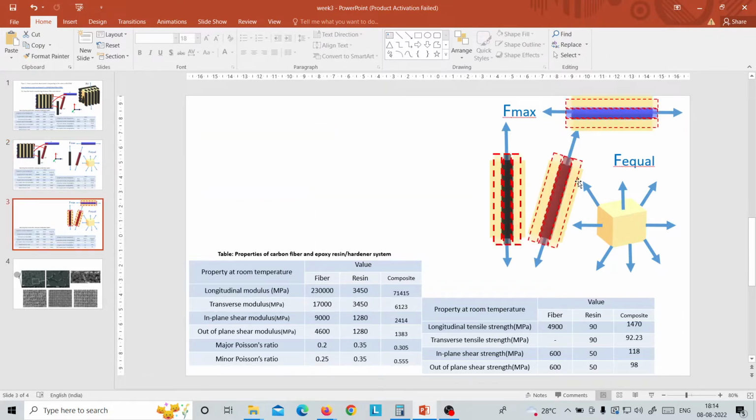Then, as I explained, if stress is generated in a fiber, it will elongate and generate a corresponding strain. Then the same thing would be transferred to the matrix, as they are both strongly bound together. This matrix will transfer stresses to the fibers present nearby, either at different angles in the adjacent layers or fibers placed parallel to that particular matrix material.